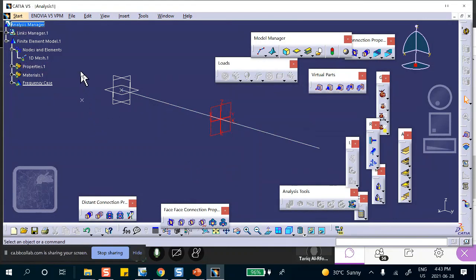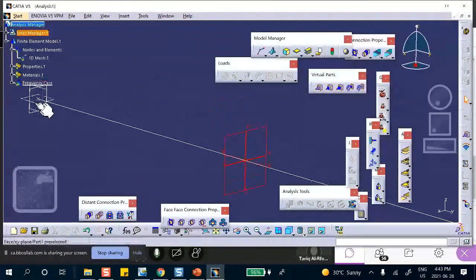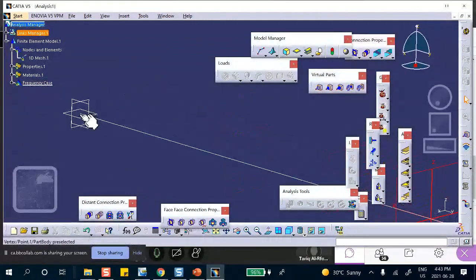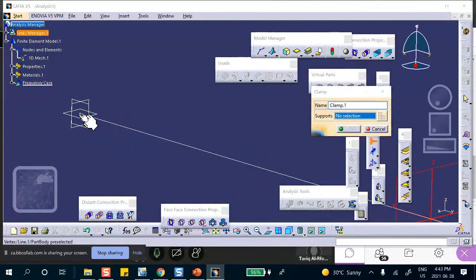If I change this into a different point up here, this will tilt. If it tilts, the beam doesn't tell you, but of course the response of the beam is going to be different. You don't put an I-beam any way you want. You put an I-beam in a very specific orientation. Okay. All right, good. So this is it. Now, restraints. This end was clamped. Remember that? Let me hide this. Make sure you hide that, because the clamp goes not on the point, on this vertex.